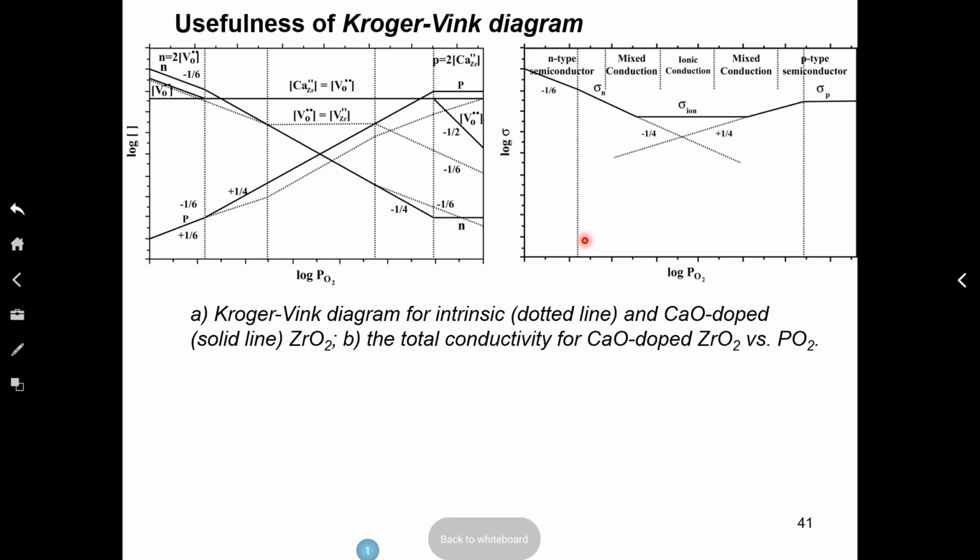This is the phase diagram for stabilized zirconia that we talked about. And remember that's an important technological material because it's used in oxygen sensors, high temperature fuel cells, and oxygen pumps. It's an interesting material. If you take a strip of stabilized zirconia, dense, density should be in excess of 90% or 95%. And then if you apply an electric field, a voltage across the thickness of that membrane, you can pump oxygen